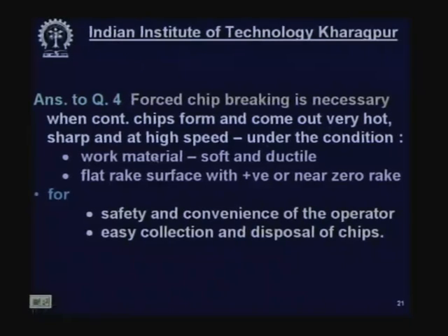Under the condition that the work material is soft and ductile, use a flat rake surface with a positive or favorable rake angle. Why is forced chip breaking necessary? Safety and convenience of the operator, easy collection and disposal of chips. Thank you. So, this is the end of